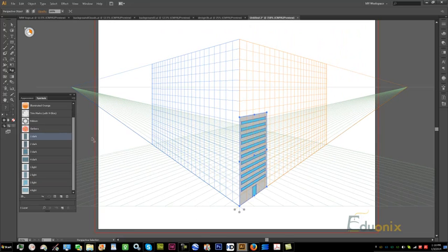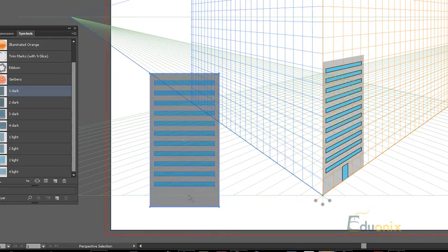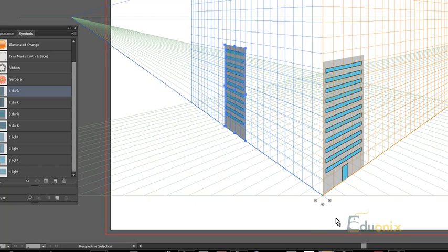So with the light one in place, you're going to take the corresponding dark one, drag it from the palette, and you're going to start dragging down here at the bottom edge. Hit 1 to put it on the left side. And if you're doing this in reverse, you need to hit the other buttons. You don't have to start on the right side like I did. Sometimes it's advantageous to start on the other, but you want this to lock into one of these grid points generally, unless you don't mind a little bit of unevenness.